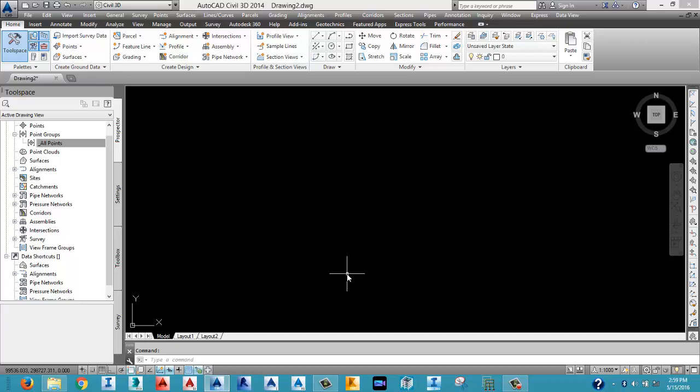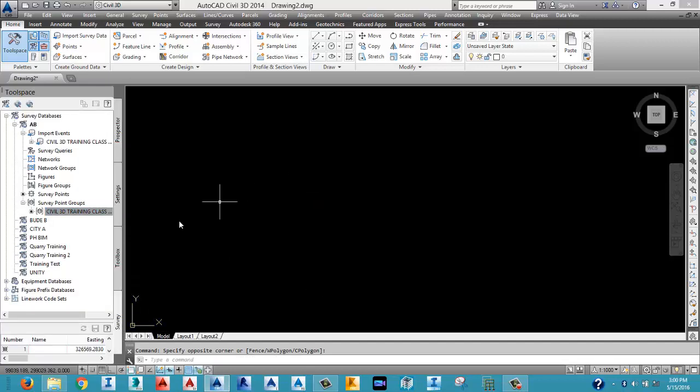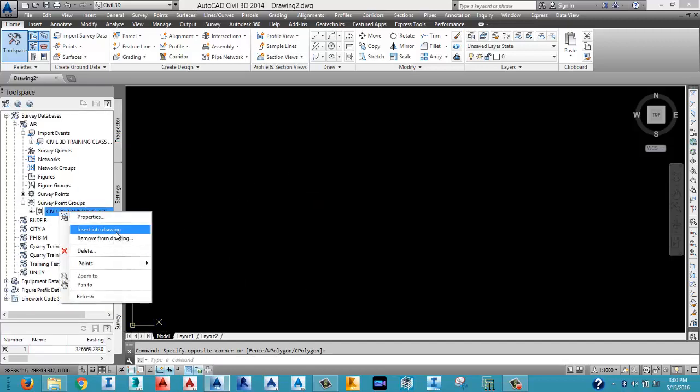Oh, your delete won't work. Maybe it's marked, because initially, assuming you get it right, your All Points group is supposed to be active. So from All Points, you just right click and tell it to delete. Like now I don't have anything, so that's why it's telling me update. So that's one way of bringing in the points, as well as going back to the survey again. I might decide to call it out again, bring it back, and then delete it.